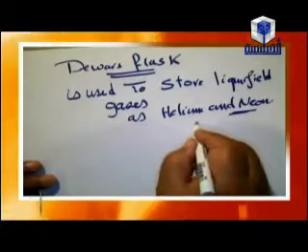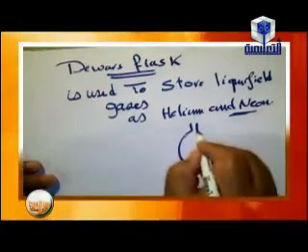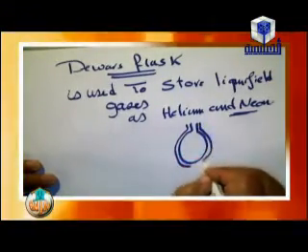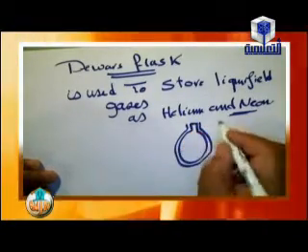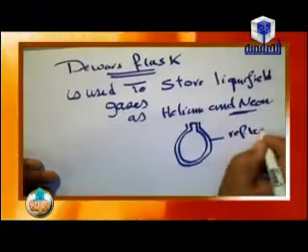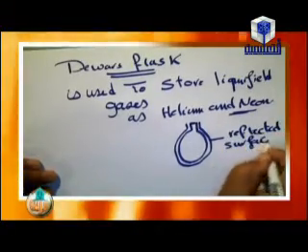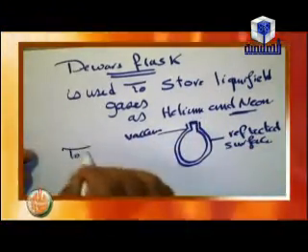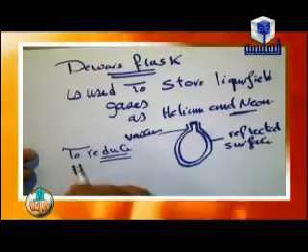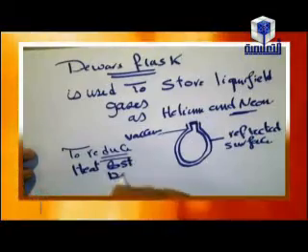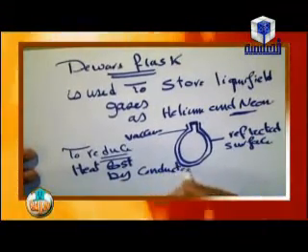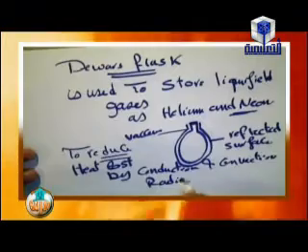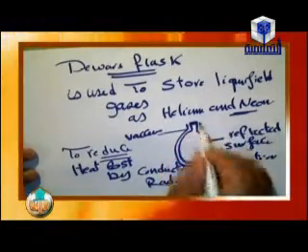The drawing is a double wall flask, between them a reflecting surface, and also vacuum, to decrease the heat lost by conduction and convection, also radiation, to keep this liquefied gas at the same temperature.